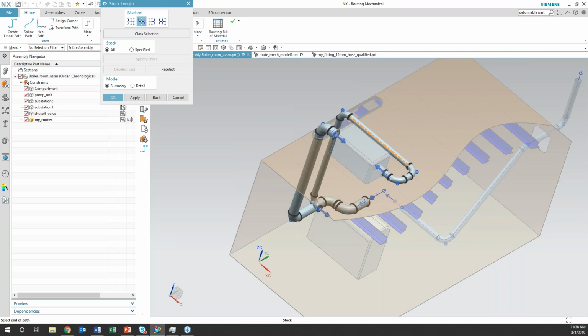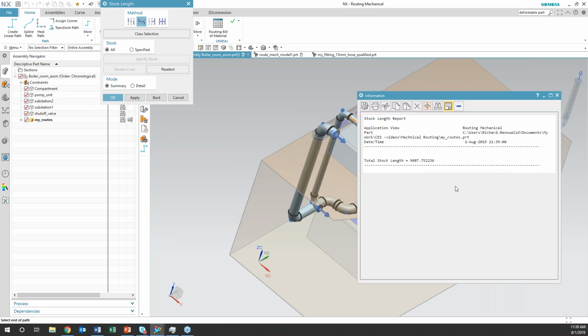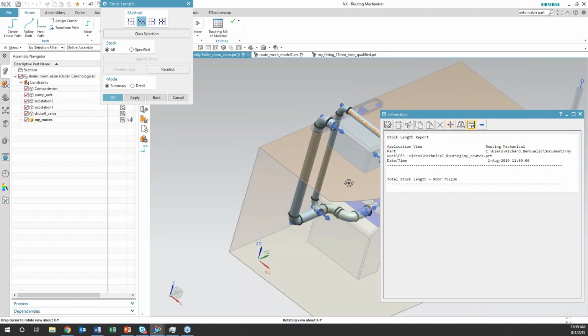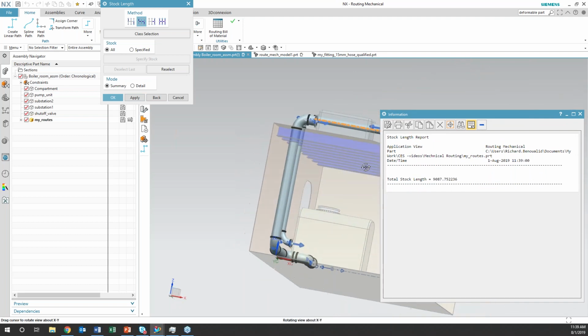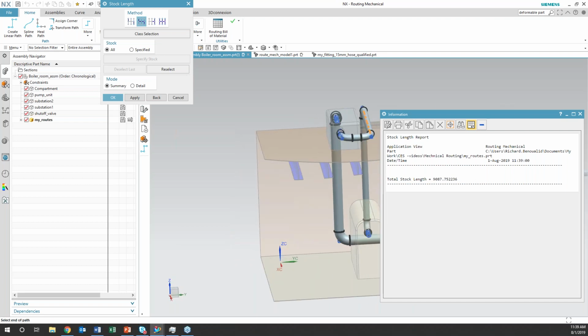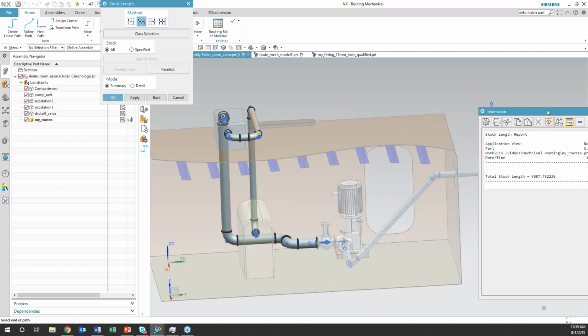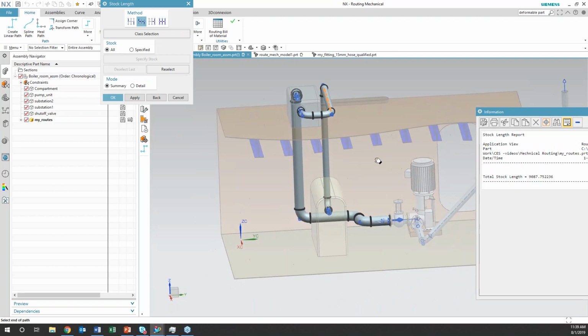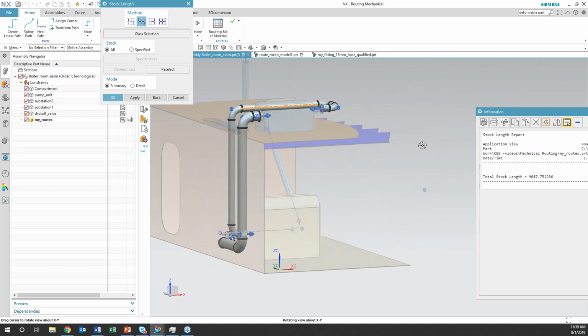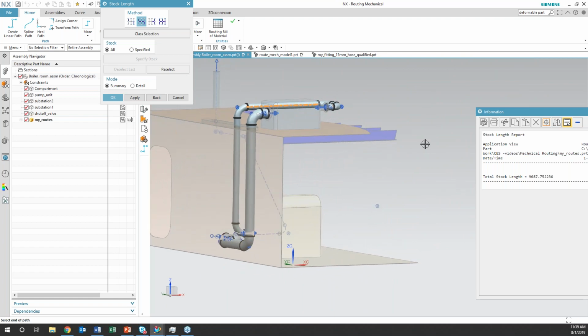Someone did have a comment here. It says it looks like the first pipe into the lower box is not straight. It's at an angle. That shouldn't be, because it's probably the angle of my window here, the way I'm showing it, because we chose X, Y, Z as those linear ways of pushing it. If that is the case, there is an align functionality. I just want to finish with showing this, but I'll show you in a second the align function.